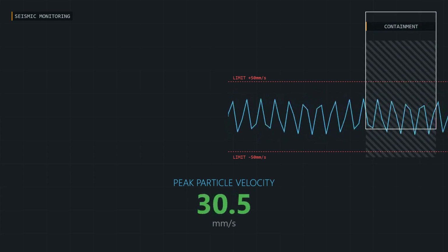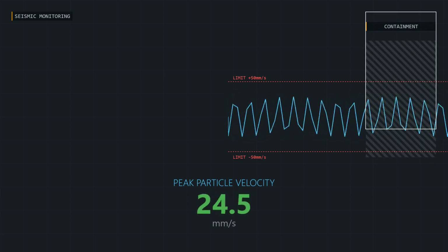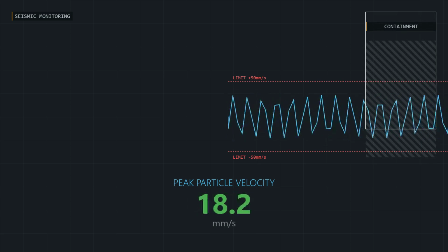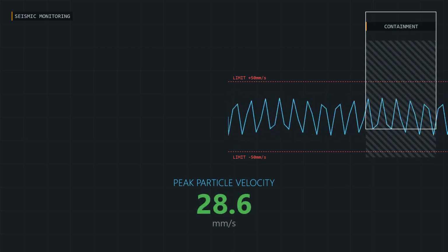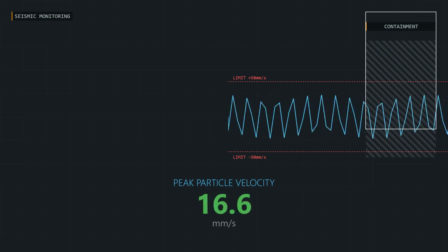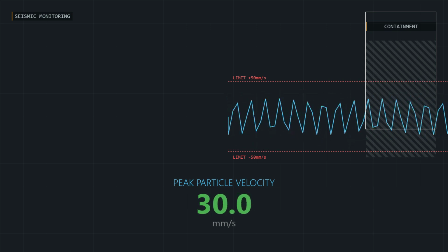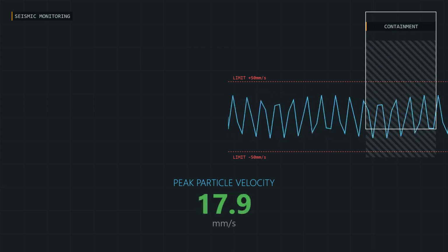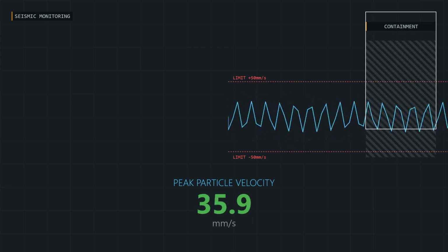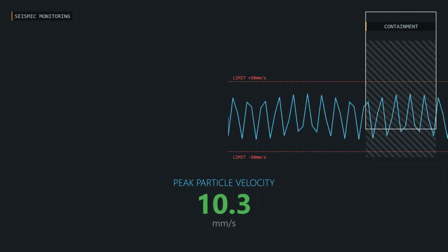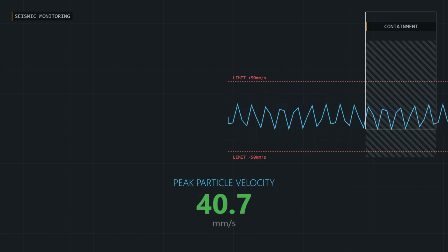Debris containment involves wrapping charged columns with specialized geotextile fabric and heavy chain-link fencing. This wrapping absorbs fragmentation energy and effectively prevents the high-velocity throw of shrapnel. Air overpressure, which is the blast wave, is mitigated by careful charge burial, a technique known as stemming, and by minimizing all exposed explosive surfaces. Proper stemming ensures maximum energy is directed into the structural member rather than into the surrounding atmosphere.